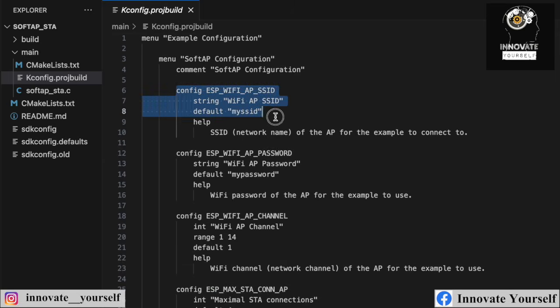So basically, what will be the SSID for your Wi-Fi when you will be using it as your access point, right? I'm talking about your ESP32. You will be using it as an access point, and what name are you going to give? In my case I will give it a name, for example, Innovate, and the password I will set as yourself, right? So this is what exactly I'm going to do. SSID and password, but right now I'm not going to write the name over here.